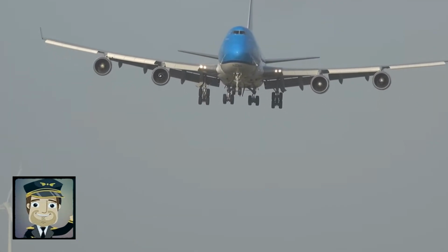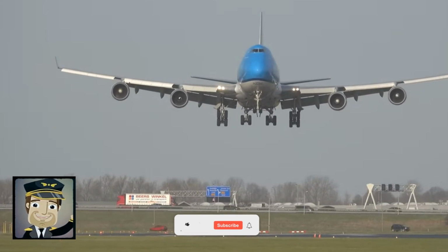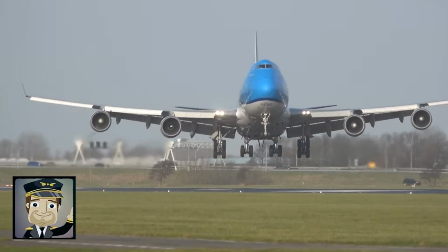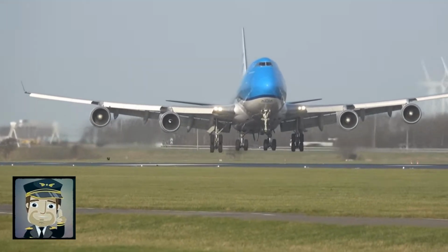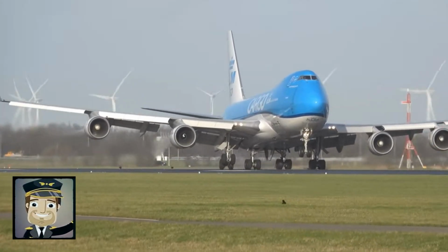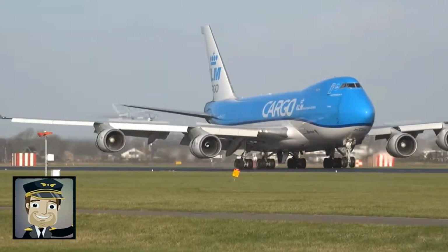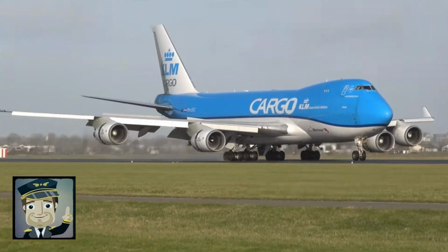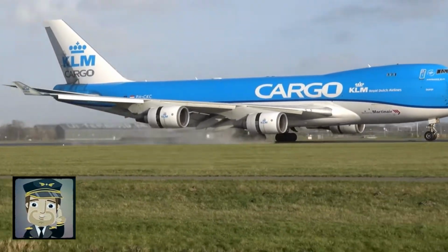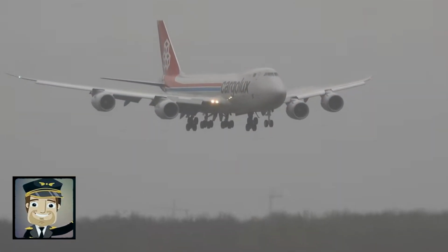There are three main crosswind landing techniques: crab, wing low, or side slip, and the combination method. Each has advantages, limitations, and ideal situations of application. Understanding each is fundamental, not only for pilots, but also for aviation enthusiasts who want to comprehend how flight science translates into operational practice. The crab technique, named for resembling the sideways motion of a crab, is the most common in commercial aircraft. In this method, the pilot points the nose of the aircraft slightly into the wind, keeping the fuselage at an oblique angle to the runway.